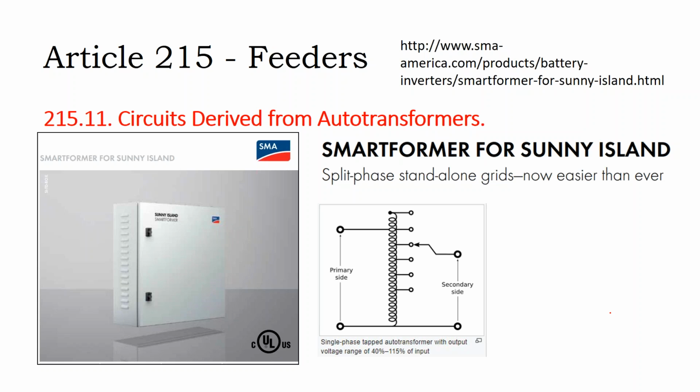It's not uncommon to have transformers on a solar array. Generally with a solar array, you're just connecting the neutral of your solar array to the grid-connected neutral, because that ground connection of neutral has already been made somewhere else. You might think, well, the neutral has to be connected to ground and I'm installing the solar array, so somewhere along the line I have to install a ground rod and connect to ground. Just keep in mind your building electrical service already has the neutral connected to ground at some point.